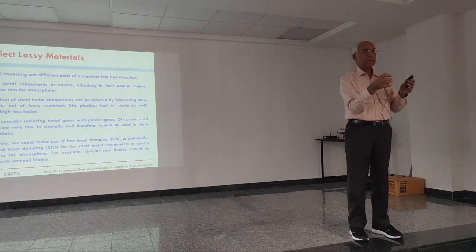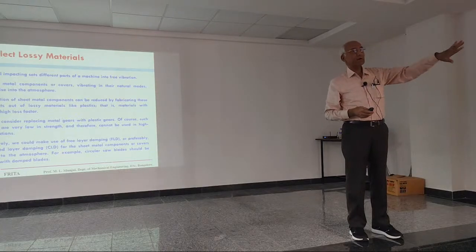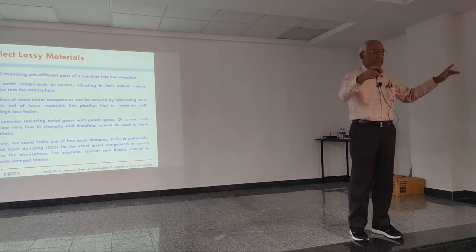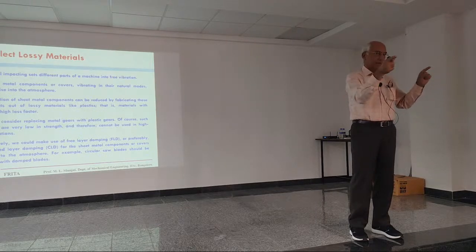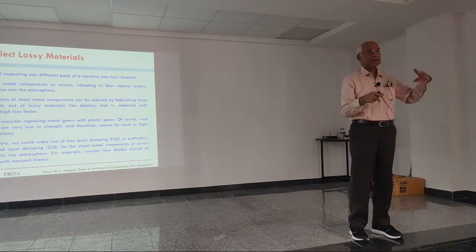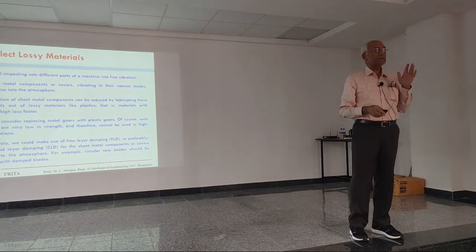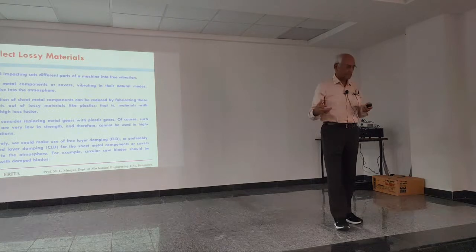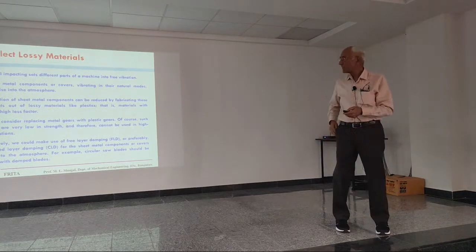The real part we call the storage modulus, the imaginary part we call the loss modulus, and the ratio of the two, loss modulus divided by storage modulus, is called the loss factor. So basically what I am trying to say is designing for more loss factor, that's what I mean by lossy materials. Alright.